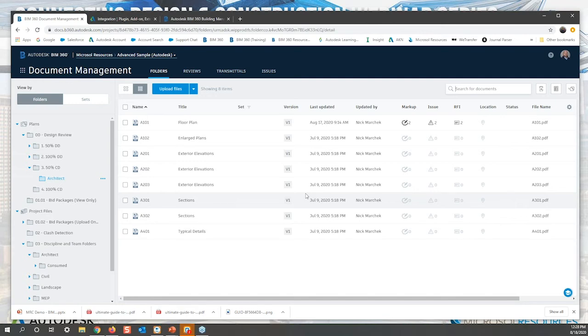So the most important thing that I want to point out here is that the use of software is not required. Let's say that you have a project manager who wants to review a Revit model or sheets being created in Revit, but they don't actually use Revit itself. If they have access to BIM 360 Docs, the project manager can view the models and the sheets, and they can also use markup tools and create issues that will be assigned to those people working on the model.